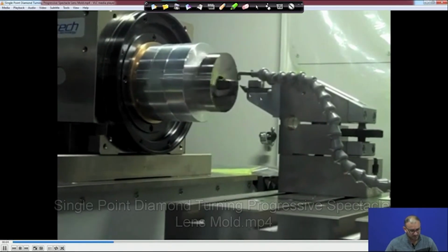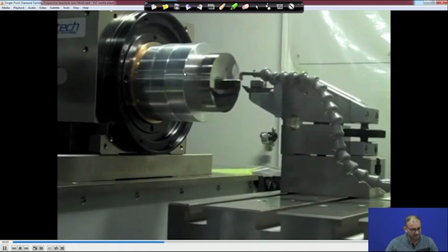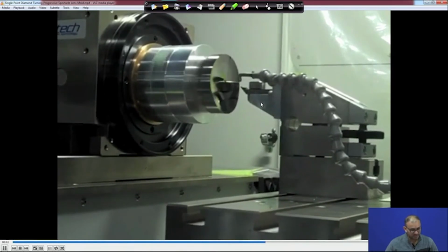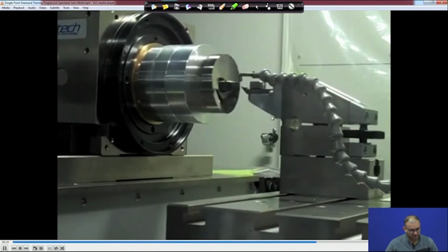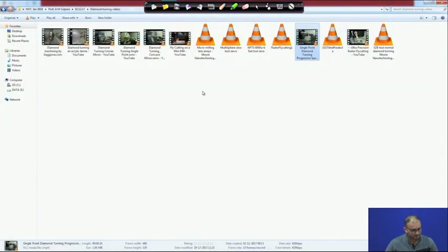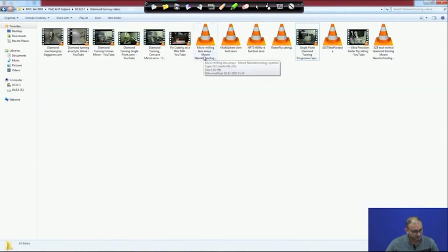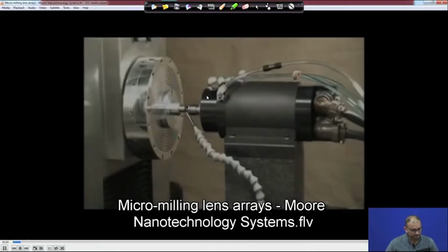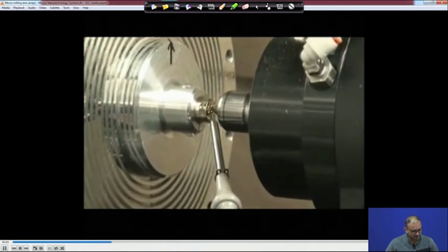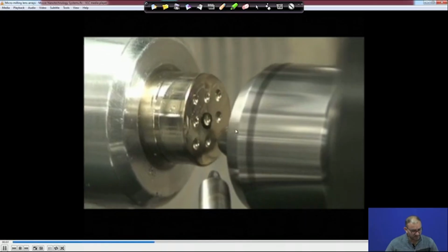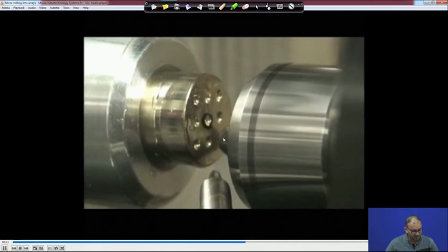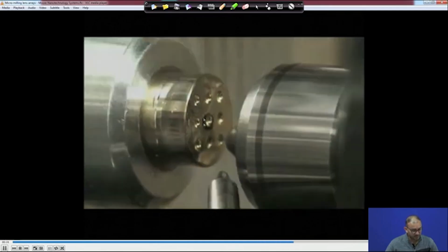Now, you can see that you have a synchronize between the rotational motion with respect to the movement in the z axis. So, these are called the servo mechanisms, fast tool servo and the slow tool servo. We will discuss this thing in detail. And suppose you want to make something different. So, here what it is doing, that here this is fixed and your z axis is working in a synchronized manner. So, the tool is now rotating and you are making different type of lenses on the surface.